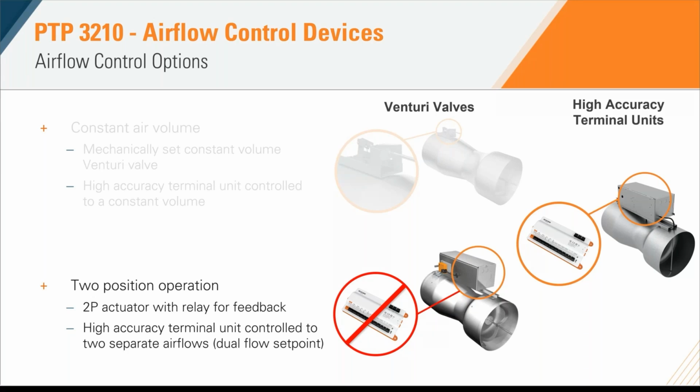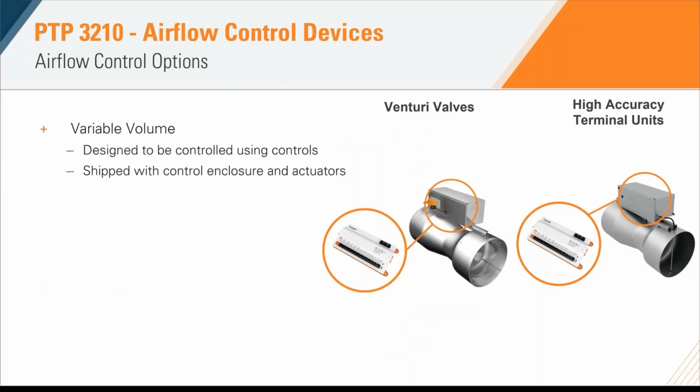So the final operation here is going to be the variable volume application. If we're designing for a fully variable volume application, we will still have to provide actuators and controllers for both the Venturi valve and the high accuracy terminal unit there.